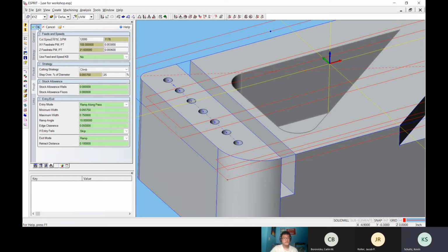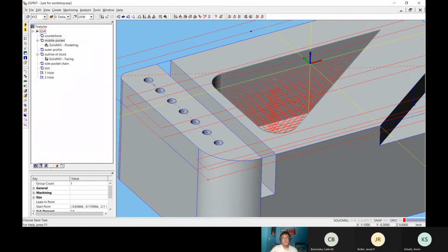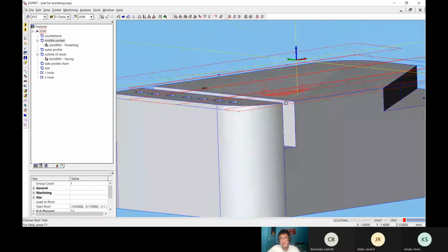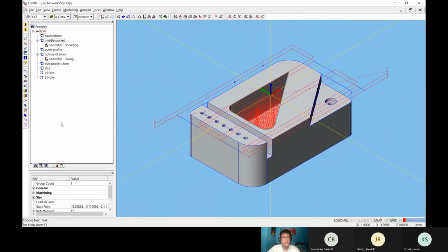Okay, perfect. And then let's see what happens when we press OK. Oop. And now we have another tool path. I mean, that looks good to me. Maybe. I guess you can only see if you run it. So let's do that. Good to also, when you run simulations, make sure nothing is highlighted in here. Otherwise, like let's say you had this highlighted, it will just simulate this pocketing operation. So just make sure you click out of it and then simulate. So press the green button and then press play.